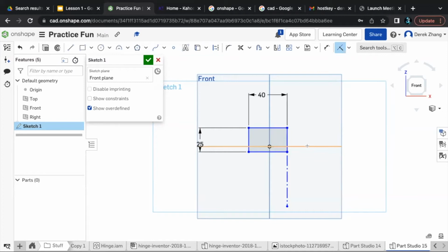It should say I, and then you hover over the middle line with the plus symbol. Does everyone see that? Now click the middle line right there, and then click the dot again. If you do that correctly, you should see the top and bottom lines are now black. This means that they can't be moved anymore. Unless you change dimensions, they're stuck in place.